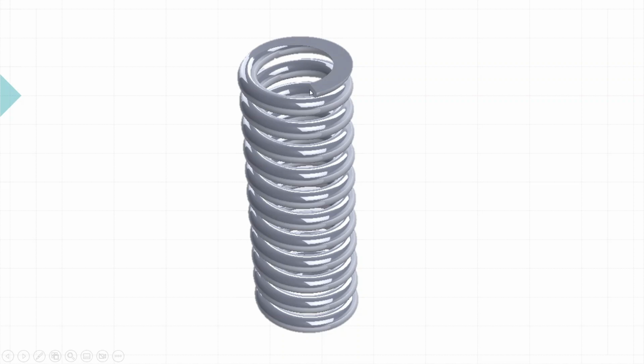Square and grounded end. The rotation will be complete so that the end touches the spring and it is closed, which is important for square and grounded ends, and the end is square. In practical life it is ground to make it flat. Both ends will be flat. So let's go to SolidWorks and design it.